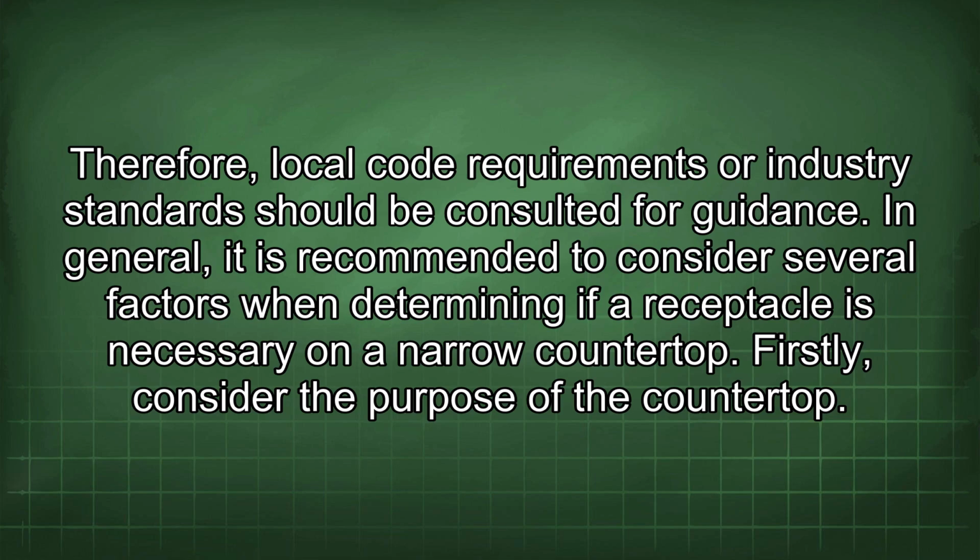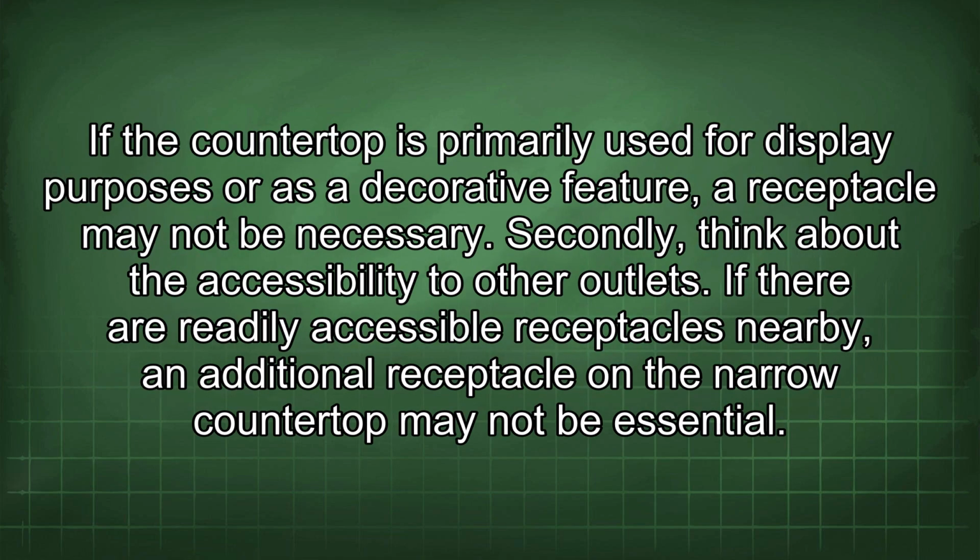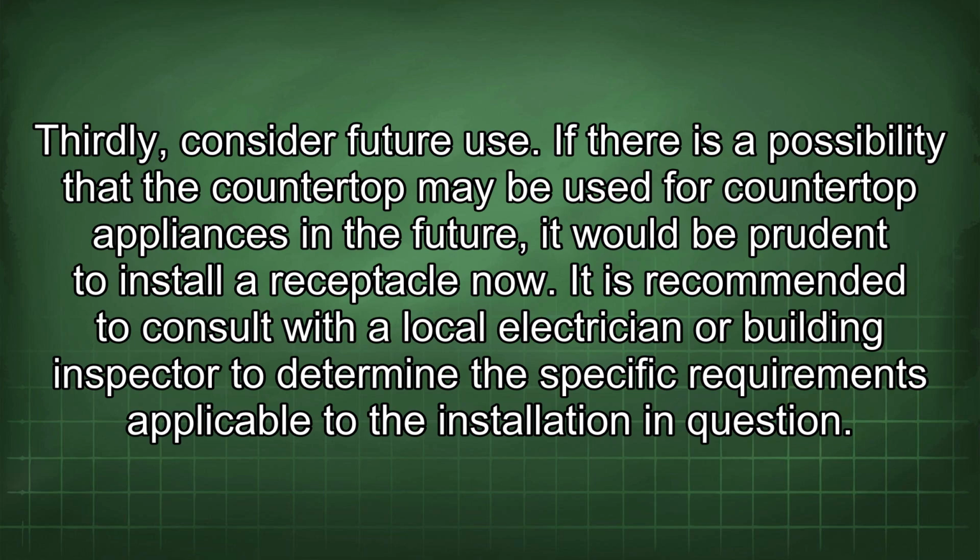In general, it is recommended to consider several factors when determining if a receptacle is necessary on a narrow countertop. Firstly, consider the purpose of the countertop. If the countertop is primarily used for display purposes or as a decorative feature, a receptacle may not be necessary. Secondly, think about the accessibility to other outlets. If there are readily accessible receptacles nearby, an additional receptacle on the narrow countertop may not be essential. Thirdly, consider future use. If there is a possibility that the countertop may be used for countertop appliances in the future, it would be prudent to install a receptacle now.